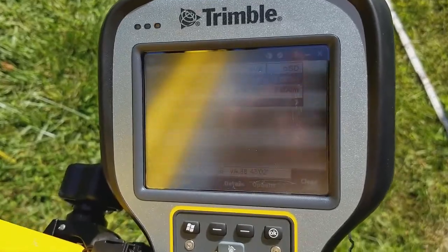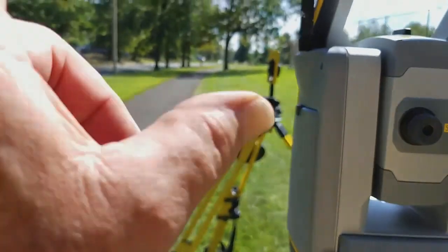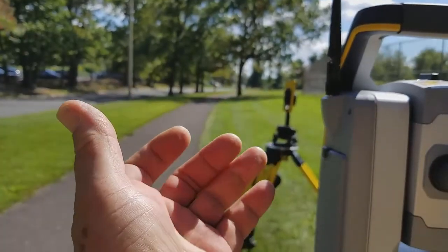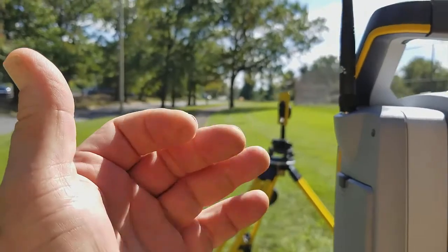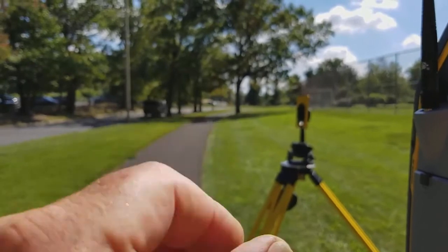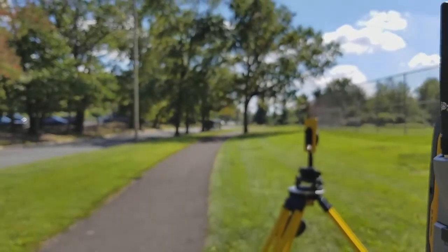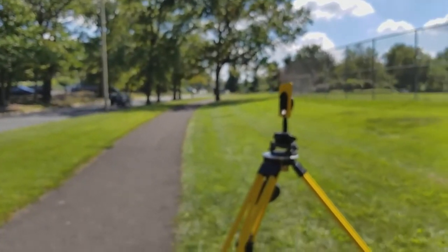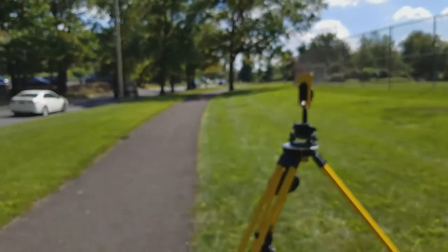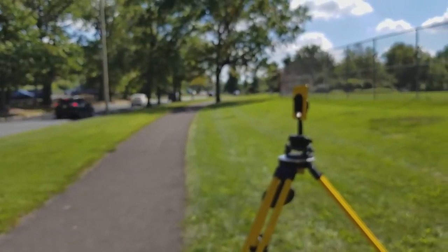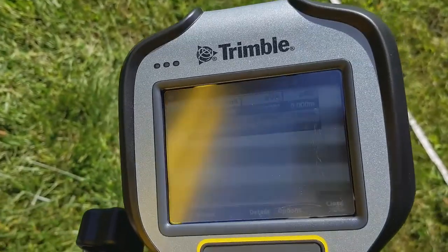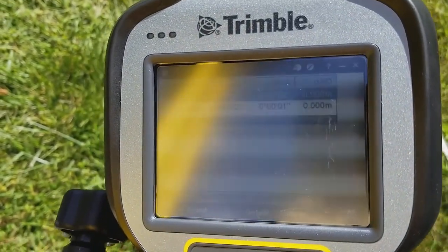The reason for that was that because of how close together they are, way back there, I was getting a return from both prisms, and it couldn't distinguish which one to lock onto. So I turned that feature off and manually pointed them myself and recorded those observations. So that's the only difference here. I took it off of the automated mode and did my own pointings, which are definitely comparable to the results of any of the others.